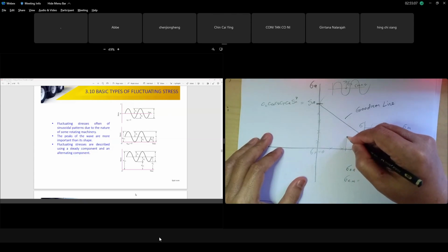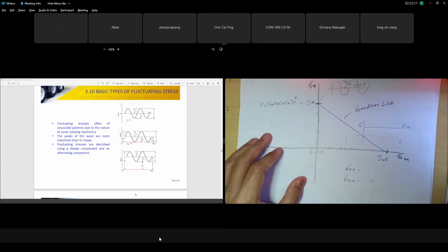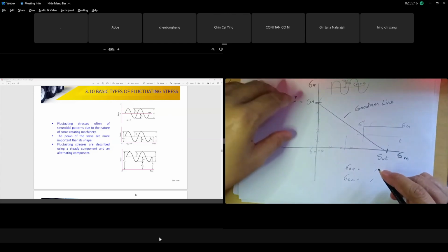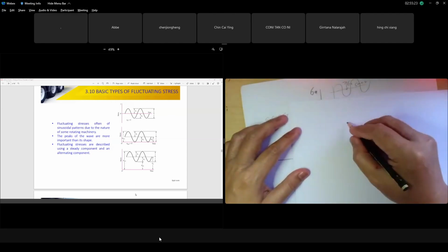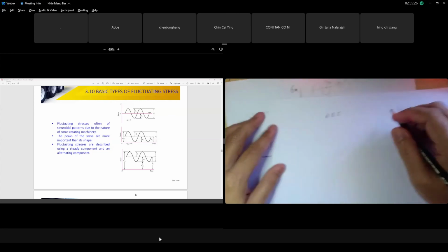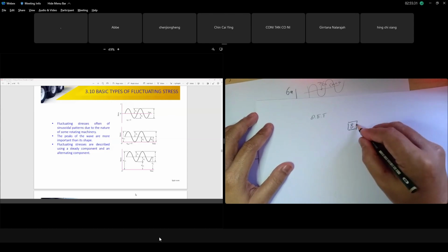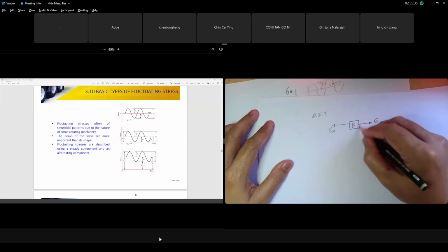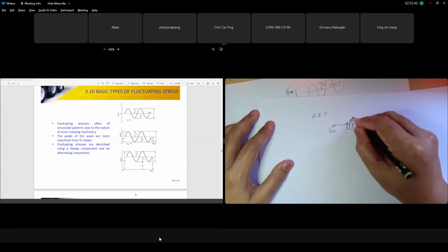Remember what I said earlier, you calculate because your force has a maximum value and a minimum, so you can find your maximum and minimum stress. But our case is sigma equivalent. Remember our distortion energy theory, DET. For example, in your shaft case, you have an element at point B. At point B, you have bending stress sigma X, and you have tau xy because of torsion.